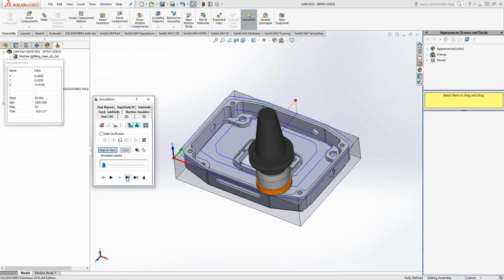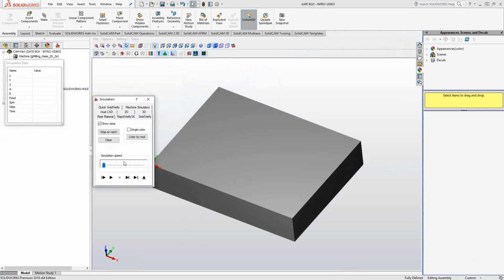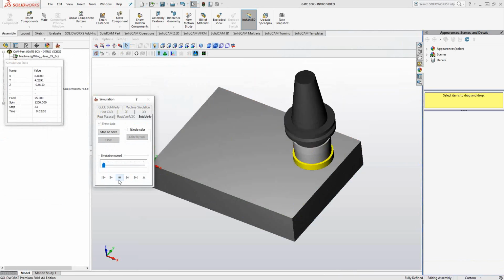If you want to do the entire thing, if it's your first face milling operation, then you probably want to do the entire stock. If I were just facing off the top surface of a part after doing drilling and pocketing and that sort of thing, I just want to take care of that particular area, then I can do so by choosing just profile geometry.